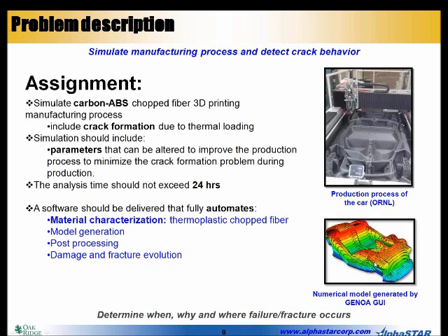To address this problem, the following assignment was given to us by the Oak Ridge National Lab, and the idea was to simulate a carbon ABS chopped fiber 3D printing manufacturing process that they are using currently. And the simulation should include the formation of cracks due to thermal loading.